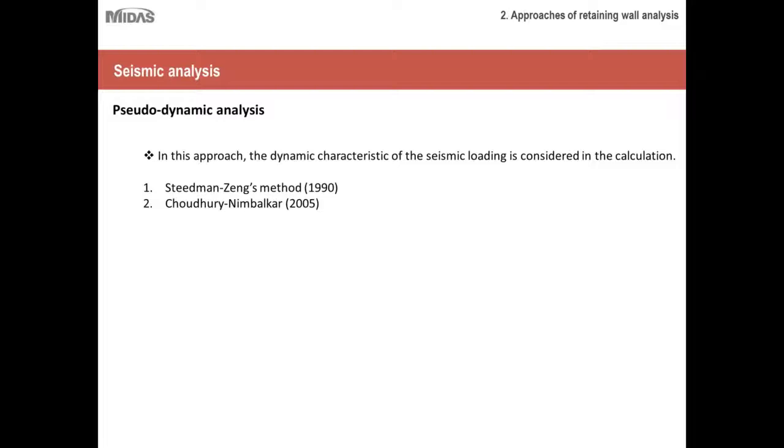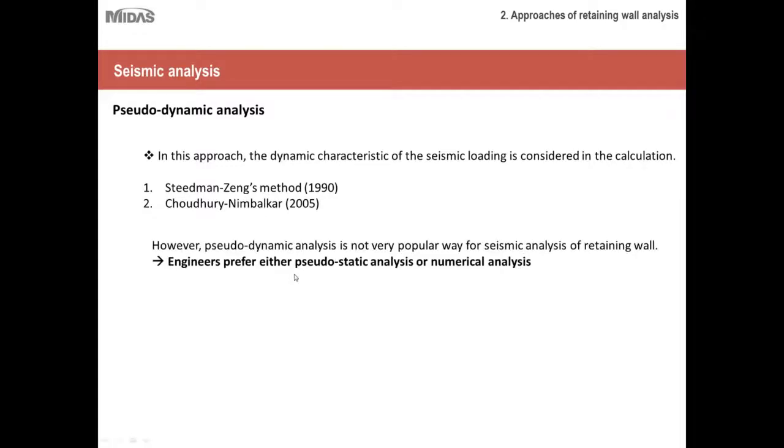Wherever they need seismic analysis, if it's a low seismic zone and they want to do some quick and easy checks, they go for pseudo-static analysis. And if they have to consider dynamic analysis, or if they have access to numerical analysis, then for seismic analysis they mostly go for numerical analysis. Here in this presentation, I've taken out all the formulas and computation for pseudo-dynamic analysis, but if you would like to read more, you can follow these two methods and read about it.